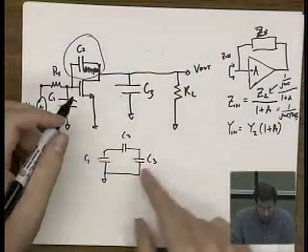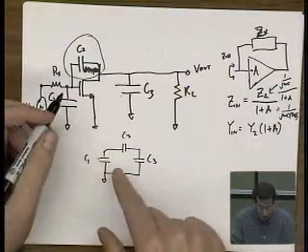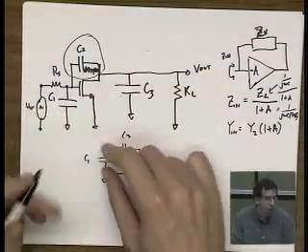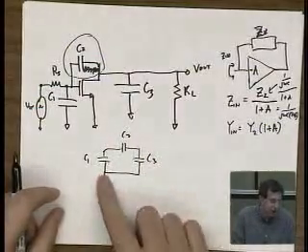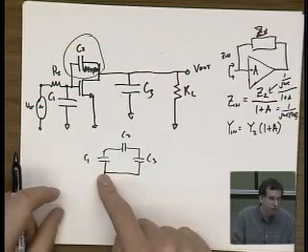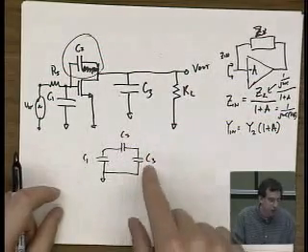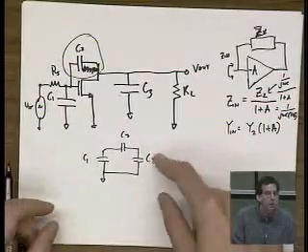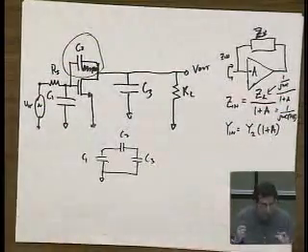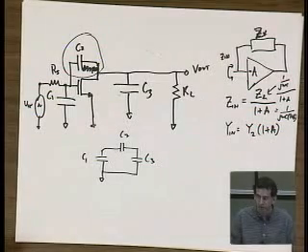Now, you can set the voltage across C1 to anything, you can set the voltage across C2 to anything, but once you do that, by KVL you've clearly set the voltage across that third capacitor, okay? So that's a handy way to look at a circuit and say, how many poles are there.